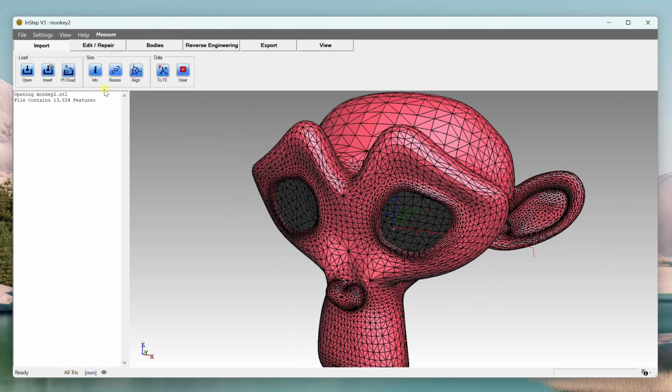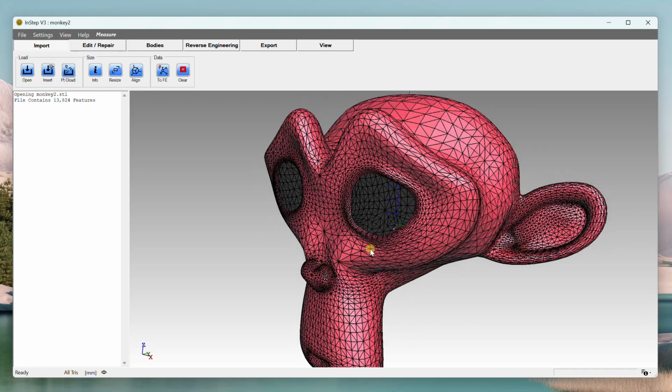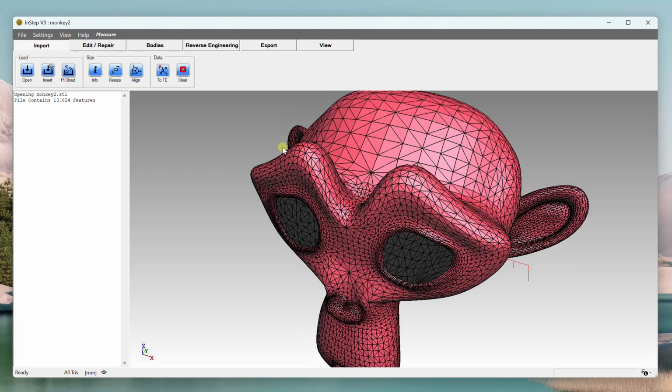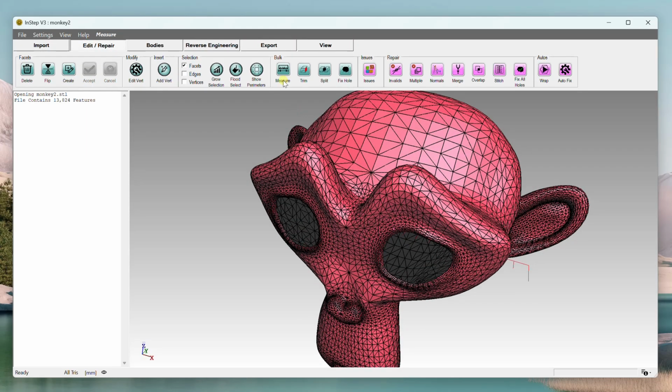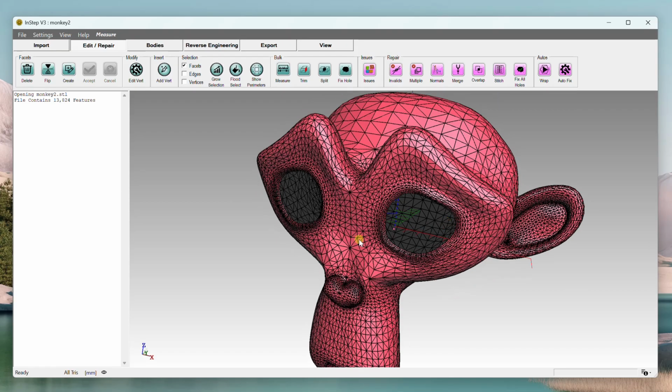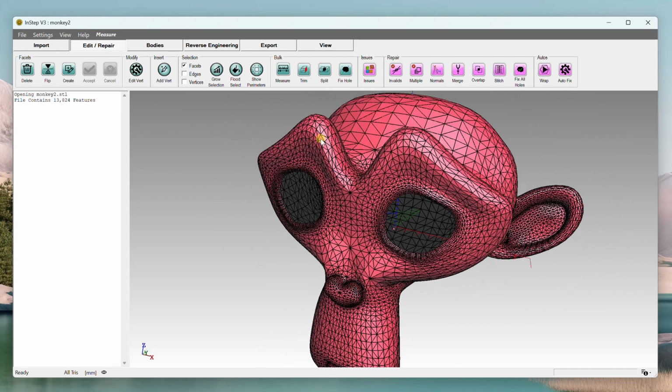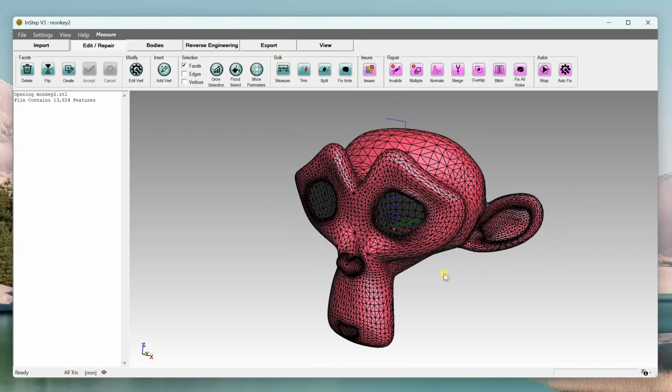So I do recommend the exporting of files frequently. Whenever I work on a project, I export several times, especially if I'm making a lot of edits. I like to do a set of changes, save it, sometimes just re-import it as well, just to make sure data is cleaned up again, because like I said, vertices and edges are not deleted in delete operations. So keep that in mind as a helpful work option there. And that's it, and we'll move on to the bodies tab in the next tutorial.